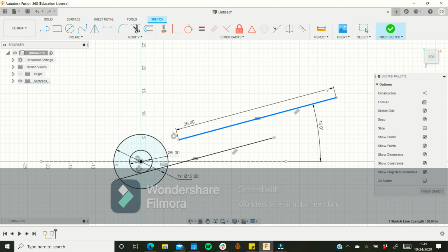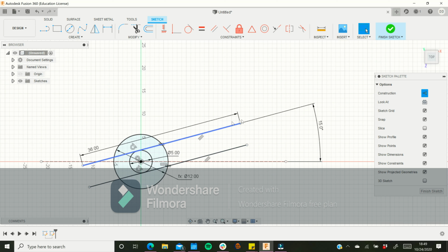I can actually, yeah, this is kind of a bad drawing because I can still move things places. Let's say I wanted everything to be completely fixed and not move like this. Let's say I want these 2 points here to be collinear. They're on the same line, and that didn't work the way I wanted it to. Let's draw a line between here and here. And now, let's just make these 2 lines here parallel because that will make this a nice rectangle.